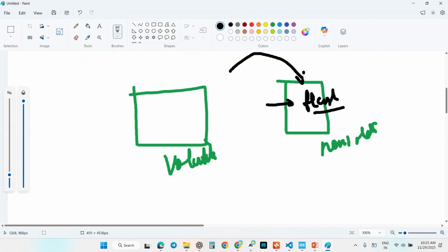When you upload this code, first of all it is just dumped into the flash memory. At the time of debugging or at runtime, your data is temporarily stored and processed. The processor uses the volatile memory because, at the time of processing, it can fetch the data easily, since it is comparatively fast. Okay, this is the common scenario.